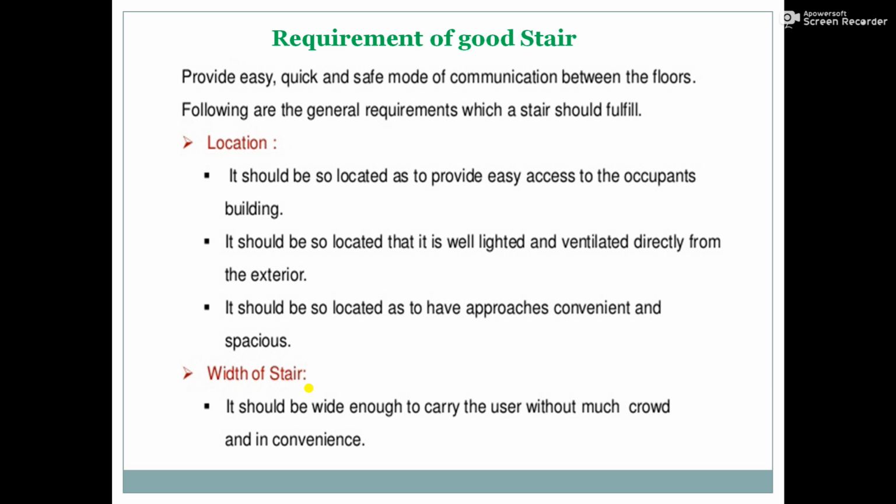So the requirement of good stairs: it should provide an easy, quick and safe mode of communication between the floors. Following are the general requirements which a stair should fulfill. So the first, that is the location. It should be located so as to provide easy access to the occupants in the building. It should be well lighted and ventilated directly from the exterior. It should have approaches convenient and spacious.